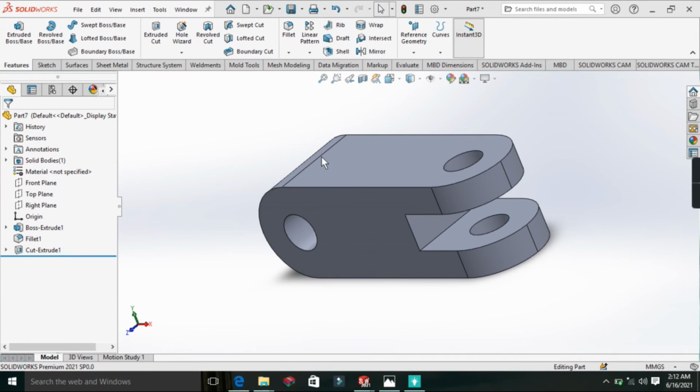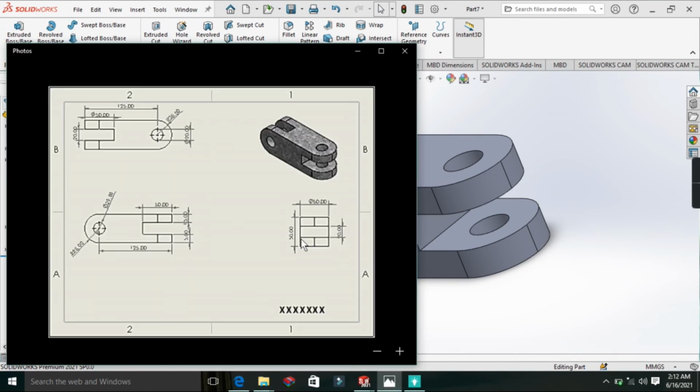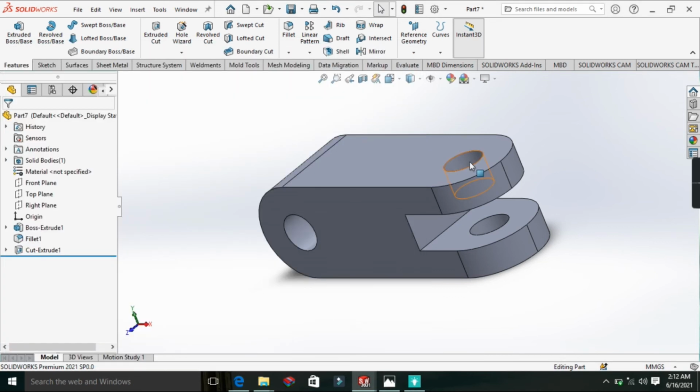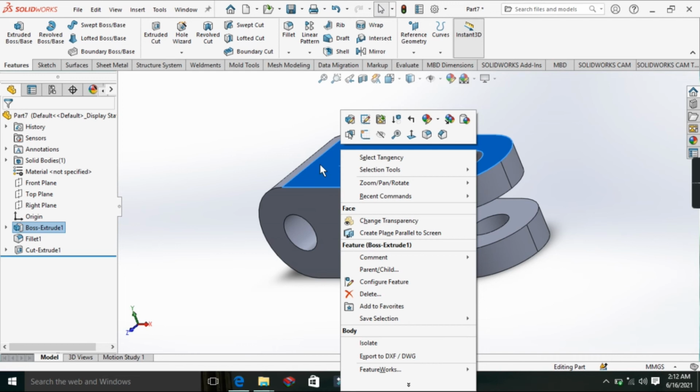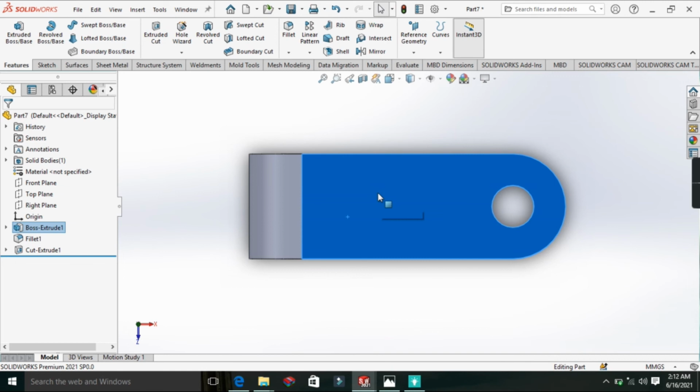The component has been designed with respect to what we have in our drawing here. But you notice that there's a cavity here too in form of rectangle when looking at it from here, right? So what are you going to do here? Like what you also did in this circle here is what you also perform. Click on this plane, you see it turns to blue, go to the normal tool and click on the normal tool. It will change the view, the convenient way you can work on.